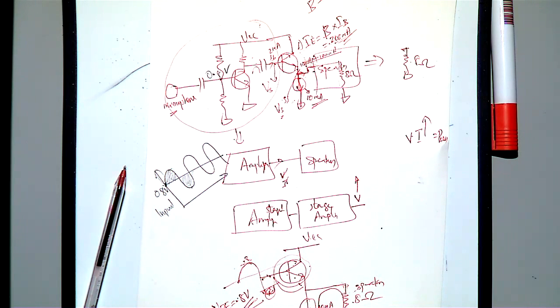So self-bias. Somebody said self-bias. So you are putting this one negative, and then you are connecting here. But then self-bias is a slight issue because your current will be very high, because you are connecting your collector directly to the base. Maybe you can connect a resistor here. One option.